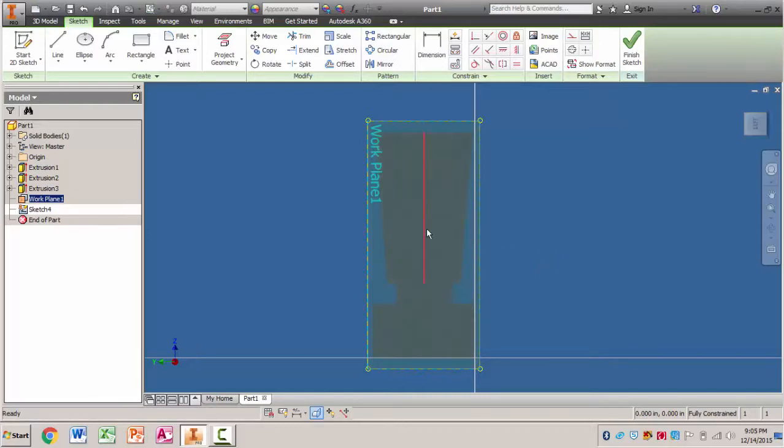You see that it kind of looks like a stone when you have it sliced, and what that does is remove all material that is in front of your work plane or your sketch that you're looking at, and allows you to see what you're doing. If I tried to draw on my sketch without having the graphics sliced, I wouldn't be able to see what I was doing because there would be physical material in the way. My first step is to project the geometry of my shape, which is what I just did. You can see the purple lines. I'm going to hit escape and get out of project geometry, because I just have to do that top area there. Hopefully you're sort of following along with the packet.